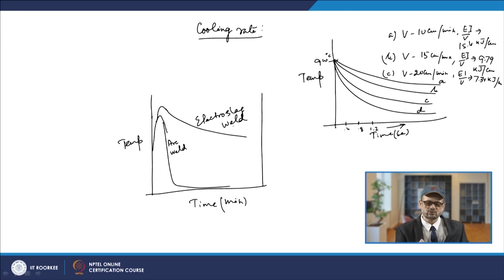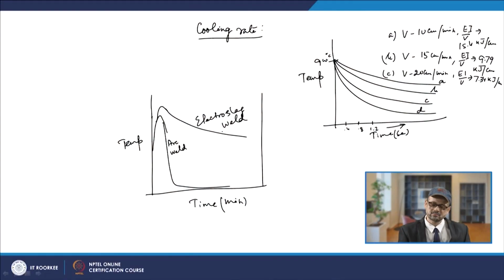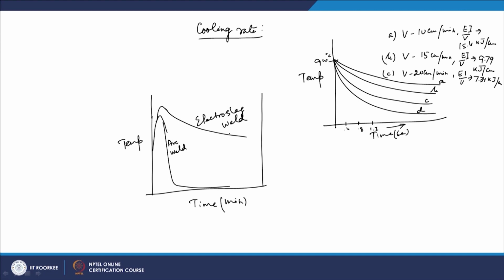As you also understand, in electroslag welding the heat input, Q by V, is very high, and because of that your cooling rate is very small.